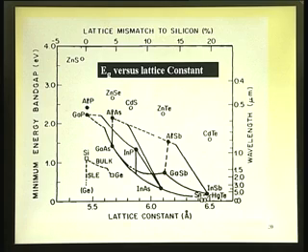And zinc telluride, if you look back into your table, I have put sulfur, selenium, tellurium in the increasing order of atomic number. So, the lattice constant also, when you mix with zinc, goes on increasing. Same way, cadmium sulphide, cadmium telluride has bigger lattice constant because of larger atom size. And same way you have gallium phosphide, phosphorus atomic number 15, gallium arsenide, arsenic atomic number 33, and gallium antimonide, atomic number 51. So, it becomes bigger and bigger.